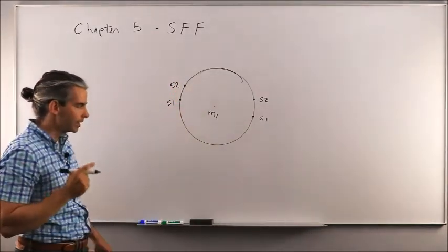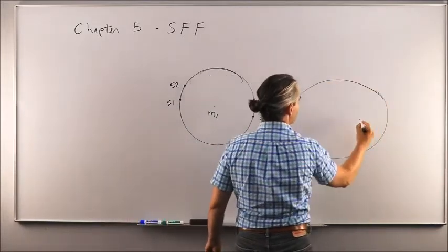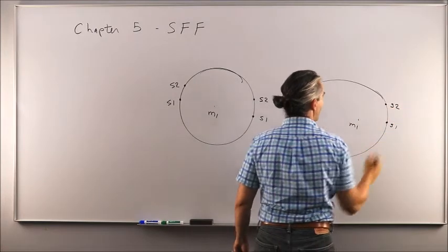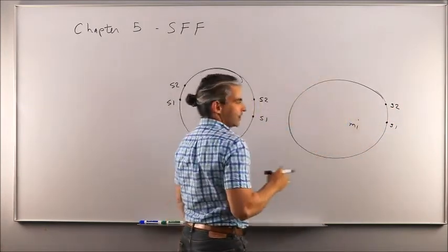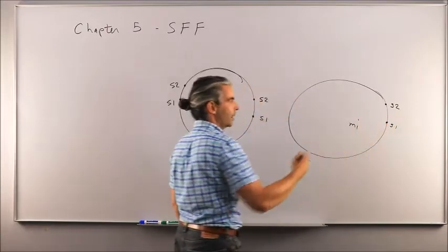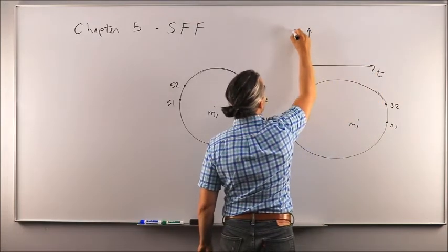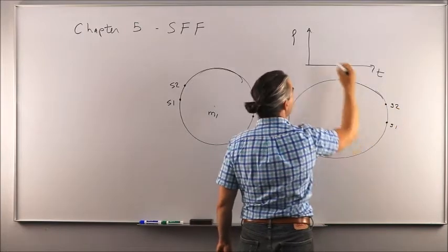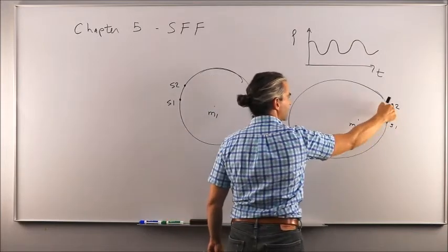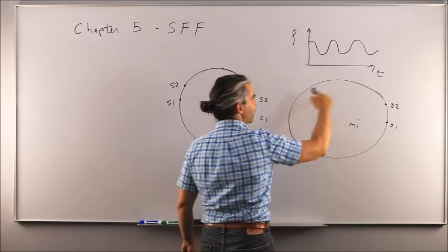the same speed. Now, another situation that can take place is the elliptical orbit case. We have spacecraft 1 here, spacecraft 2 there. Because they're riding along the same orbit, but this time the orbit is elliptical, the separation distance between S1 and S2 will vary as time goes by and will follow some sort of a sine wave pattern. If you denote rho as the relative position between S1 and S2, it would be bounded yet would oscillate over and over because spacecraft 2 is ahead of spacecraft 1 and therefore would experience a decrease in velocity here near the apogee ahead of time than spacecraft 1.